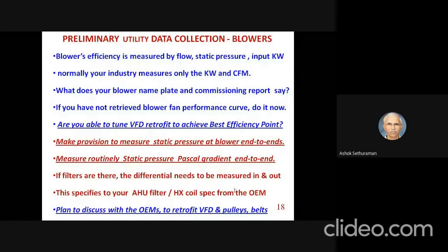Coming to the blowers, it is an eye-opener for us. Every industry or every retrofit by OEMs, they do a lot of changes in the impellers, and they say we have measured the flow before and after, they have achieved savings, the kilowatt has come down by 20%. But we found the static pressure dropped so heavily. The blower's efficiency is measured not only by the flow, it has to be measured by the static pressure in pascals and the input kilowatt.